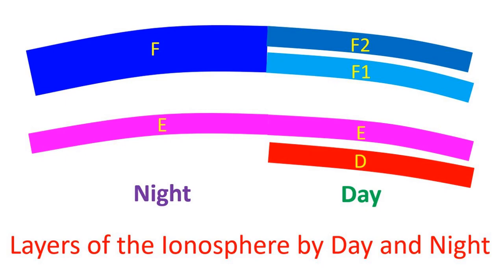You have to have some basic knowledge about which band is good at the particular time of the day and year, as well as the solar cycle. In general, higher bands perform better during daytime and lower bands better at night. Higher bands perform better when the solar activity is more, and lower bands perform better when the solar activity is lower. That is due to ionospheric reflection properties depending on the level of ionization.